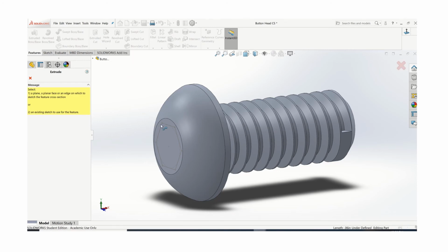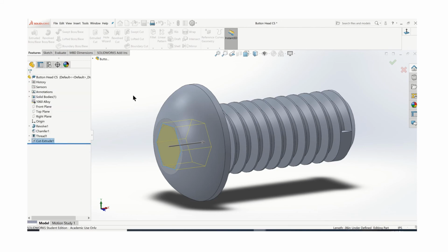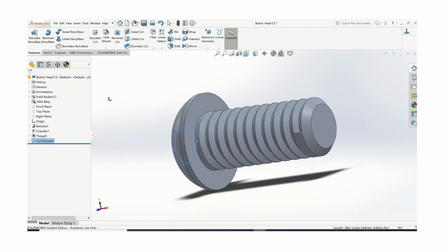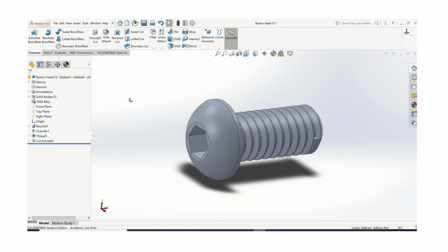The depth on that was 80 thousandths. Again, that came out of that chart I was looking at, and those will say minimums on those charts. So that's the space you have to put your wrench in there. Obviously you can't go too deep into that because it would weaken the bolt. So there is our threaded fastener.